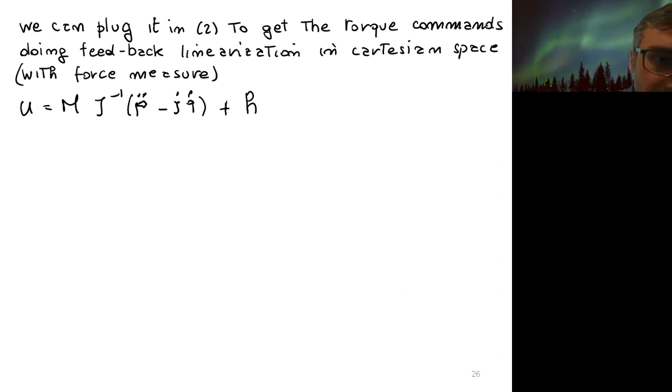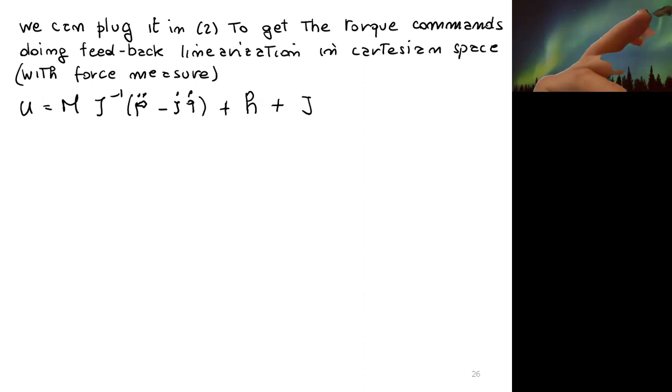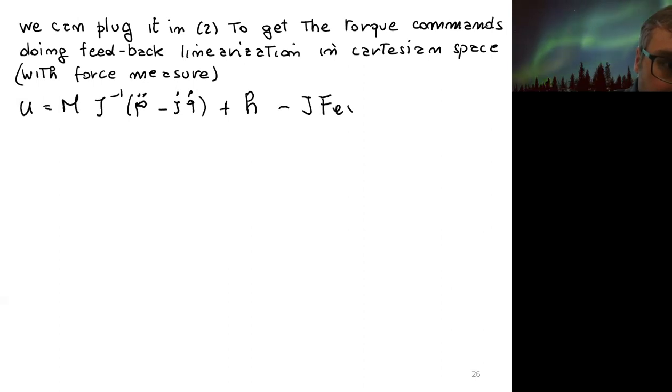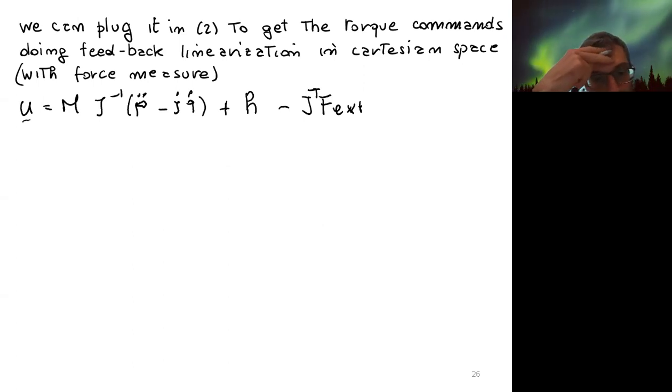I want to cancel the Coriolis and centrifugal terms, and I want to cancel the contact forces. Note that we have a minus here because the torques are on the same side as the contact forces. So if you want to cancel them, we need to do the sign change.